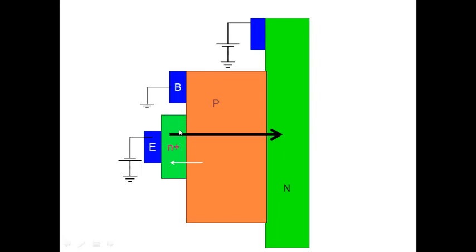All the electrons that you inject, they all end up here, and the field then pulls them into N, and then the electron comes here. Once the electron comes here, then of course it's an N-type region. It's like a resistor. It flows into the contact. All right, so you can see here that we have connected two diodes together, but we have not connected them simply through a wire. We have fused them together. And this fusing them together is what is bringing out this linkage now. Remember, earlier the two PN junction diodes were independent. Now the two PN junction diodes are linked together. And they're linked together by this current here. Whatever current you inject here, the same current ends up flowing here. Okay, so this is the linking current here. It links the two diodes together here.